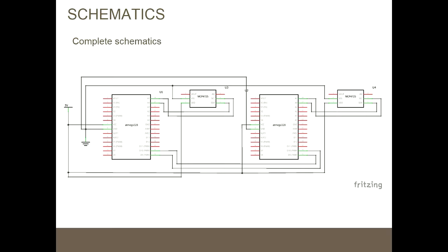So in order for this to work, we have the CPE301, which uses the I2C protocol, connected to one Atmega and the other one connected to the other Atmega. The two Atmegas are connected to each other using one of the input and output ports. Now, it is possible to have one Atmega connected to 2 DACs. The reason I didn't do it is because it required me to solder and cut some pull-up resistors that I didn't want to take the chance to do, due to resources being limited or taking the risk. If I had plenty of them, I probably would try, but since this DAC was not manufactured as such but integrated onto a board, it was already set to these addresses that I couldn't change without doing some physical modifications to it, which I wanted to avoid.